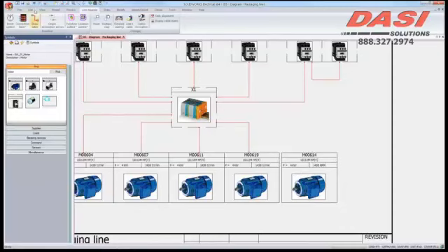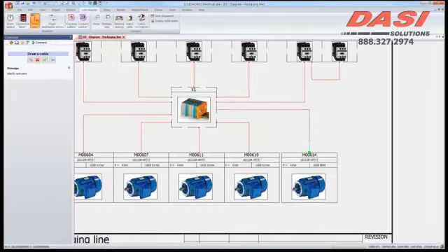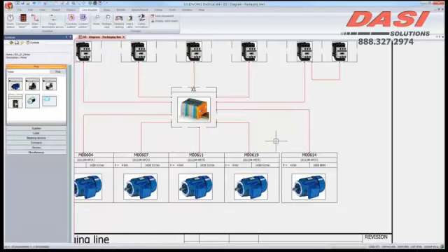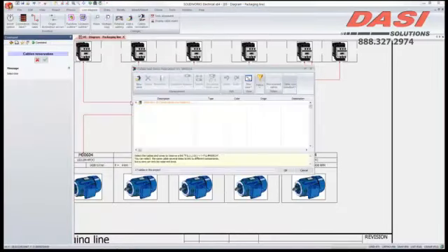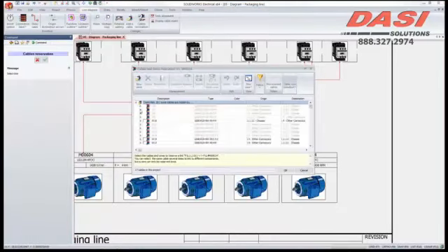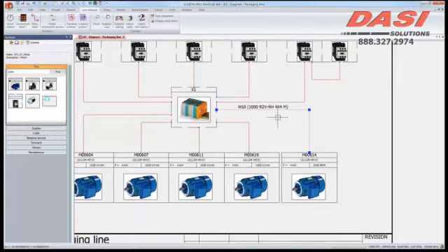Now mind you, I've already associated the manufacturer's parts, so that entire set of metadata in the library automatically populates this symbol. I could then go ahead and do something like drawing a set of contacts here, or drawing a cable. When I draw the cable, I can then actually detail the cable, I can reserve the cable. In this case, I've already got a cable here that I have reserved, and it's got 4 cores. So I'm going to go ahead and associate it, and when I do, the cabling is already available here.